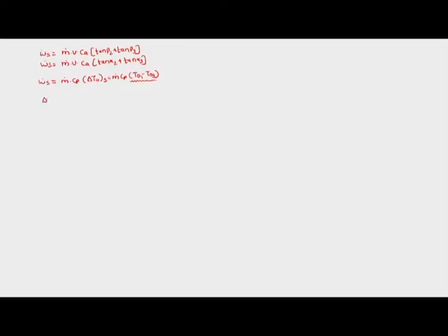So the temperature drop in the stage is equal to u Ca upon Cp into tan of alpha 2 plus tan of alpha 3. Or we can also write it as u Ca upon Cp into tan of beta 2 plus tan of beta 3. We can write either expression for the temperature drop in a stage.